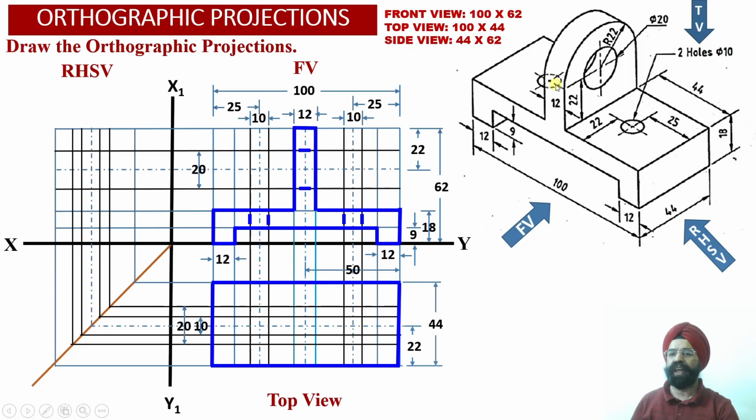So even though this vertical web is carrying a semicircular surface at the top, this semicircular top surface of the vertical web will be projected as a rectangular apparent shape projection into the top view, because the semicircular web is not parallel to the horizontal plane. So we are going to obtain a foreshortened apparent shape projection corresponding to the semicircular web, appearing as a rectangular projection into the top view projections over here.